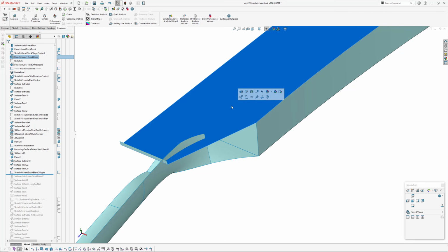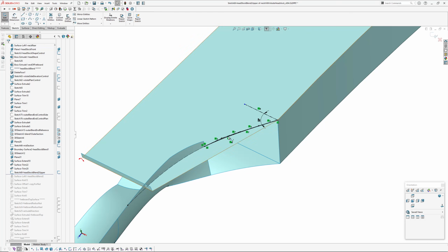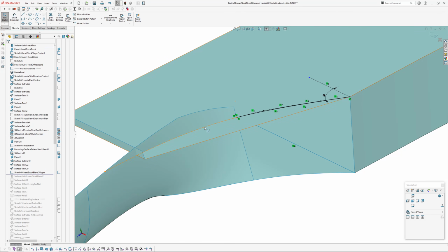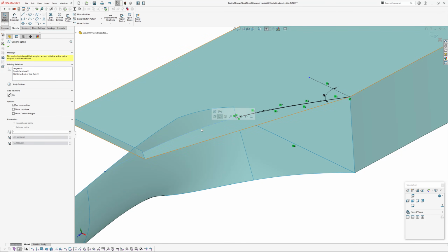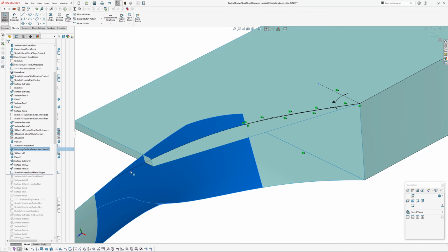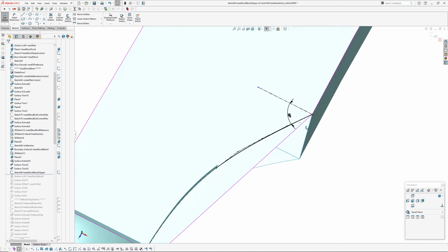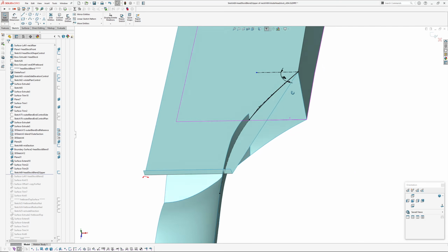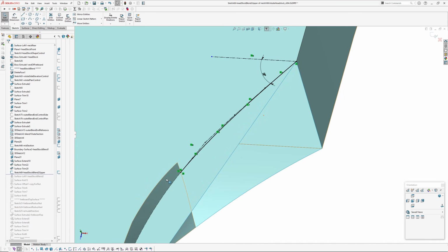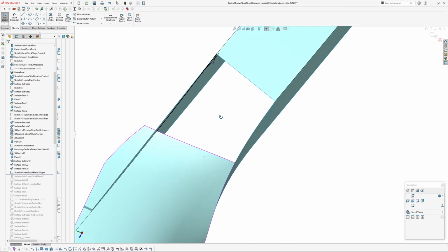Okay, and then on the top of the headstock here, I've created a sketch for my second blend, which is this headstock upper blend control. So there's an intersection curve there, which is a reference for us to get our curvature continuity on this end. So it's curvature continuous to the intersection curve of that surface, and this end is free, so I've got an angle here. Again, this is for tweaking this surface depending on what sort of fullness or curvature you want around the back of the volute here.